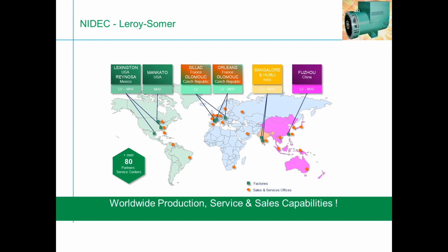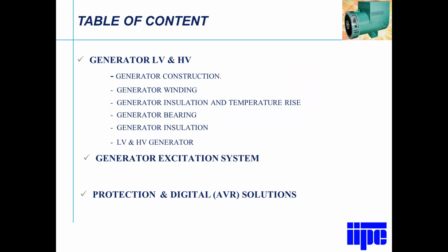Going into today's topic, we'll be talking about generators on low voltage and high voltage: how the generator is constructed, how the winding is done, whether LV or HV, and generator insulation and temperature rise, which is very important. Generator bearing, whether it is a single bearing or double bearing generator, and generator insulation for LV and HV generators. We'll be specifically touching on HV generator insulation also.